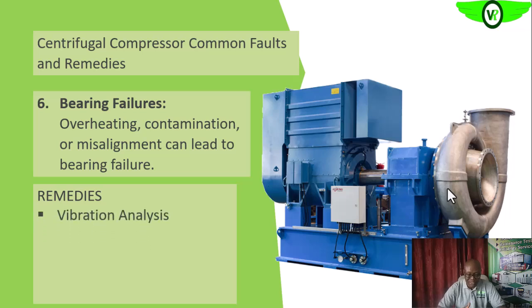So what are the remedies? We want to carry out vibration analysis so that before it gets to a stage that will affect the operations of the compressor, we would have seen it and taken the necessary step to remedy the situation. Then lubrication too.